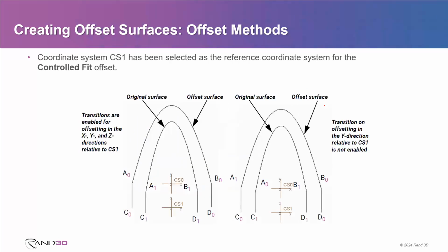Now with the automatic, you're letting Creo automatically figure out how to scale down the surface and translate the scaled down surface so it looks like an offset. You might not like how it does the translation. In this example, when I go to my automatic fit with that value of 30, I'm going to notice that my offset surface is kind of translated down. If you notice, the side edges are not horizontal with each other. I have a little taper on the side edges. If I was thickening that, the solid geometry would have those red edges.